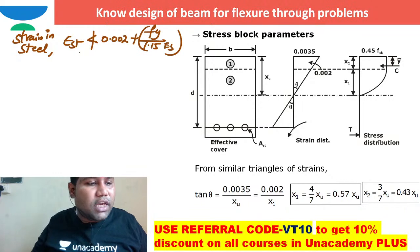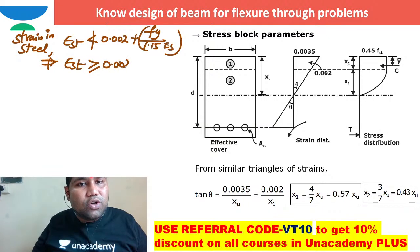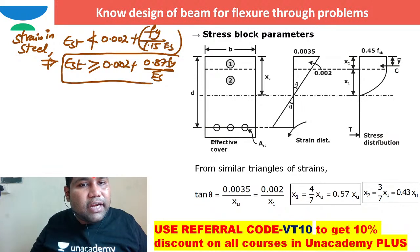So the strain in steel should always be greater than 0.002 plus fy by 1.15 Es. Can I write it as 0.87 fy by Es? Yes, I can write it that way.